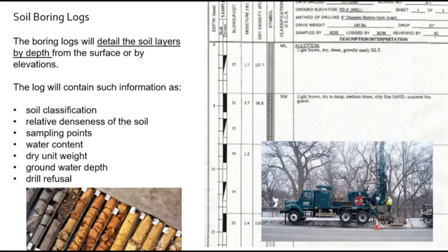Soil boring logs are created by geotechnical engineers. They are typically the first on the site. Here's a boring rig. They will drill down into the earth a given distance based on the anticipated needs of the foundation and the anticipated soil types and soil conditions. They will bring up earth samples like this in a big linear fashion, and then they will turn that into a log, which is here. And we will look closely at one of those in a moment.